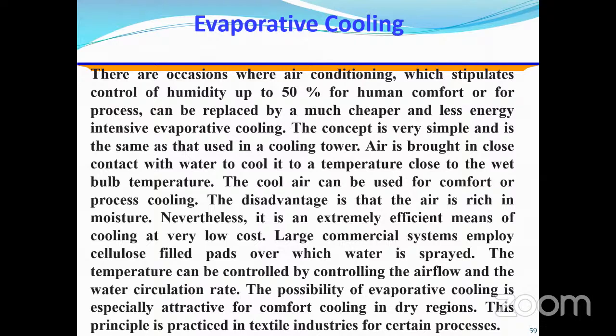Air is brought in close contact with water to cool it to a temperature close to the wet bulb temperature. The cooling air can be used for comfort or process cooling. The disadvantage is that the air is rich in moisture. Nevertheless, it is an extremely efficient means of cooling at very low cost.